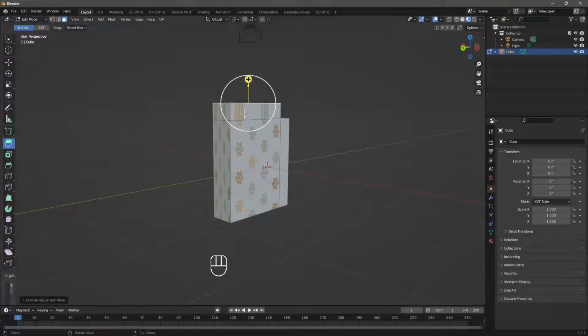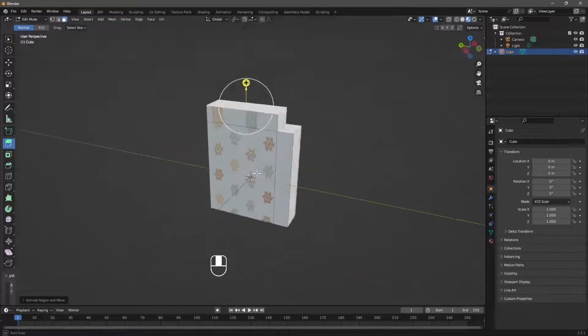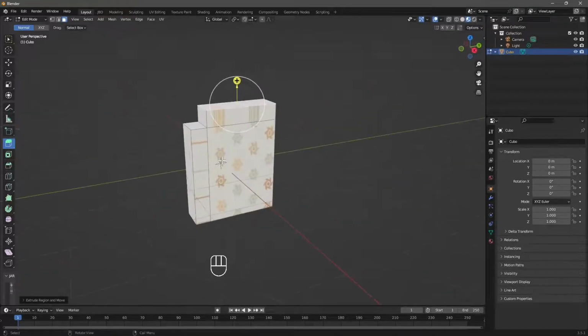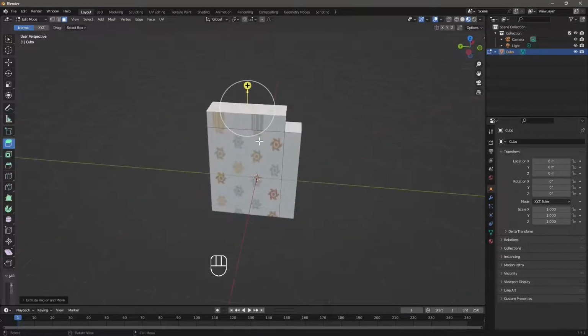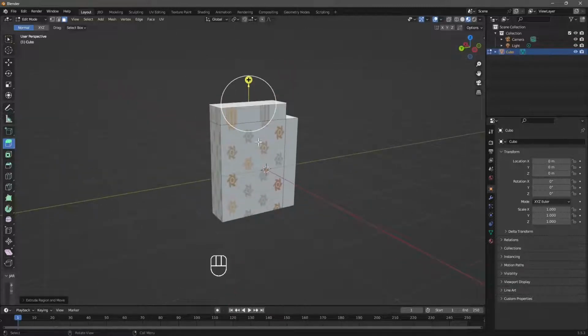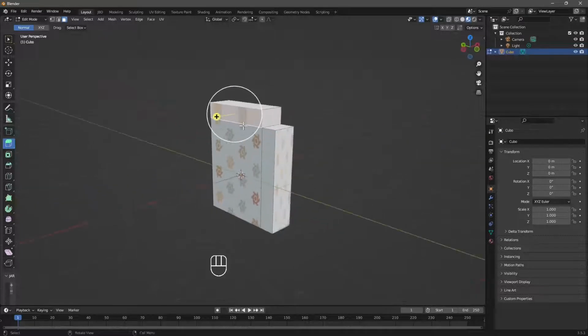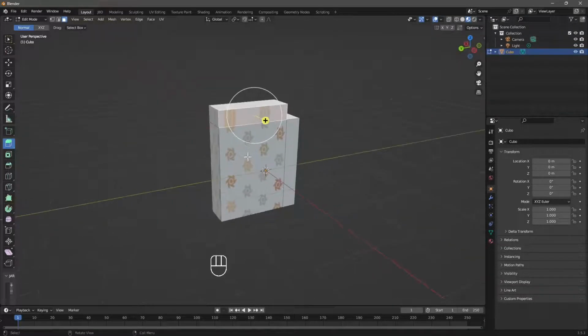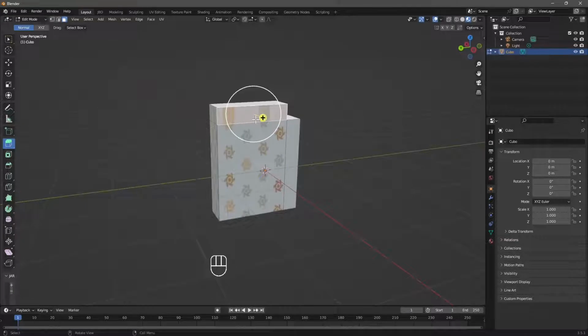The texture is stretching, and something is wrong with the packaging. It's not working anymore because I now have another object. So I cannot use the same unwrap map with a different object that has different sizes for the faces and also extra faces that it didn't have before. So I need to recreate the unwrapping. I need to recreate the unwrap map.